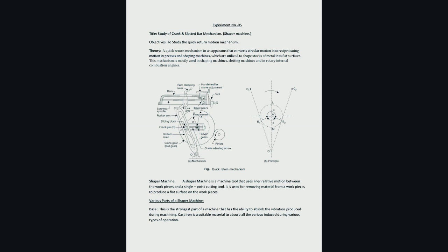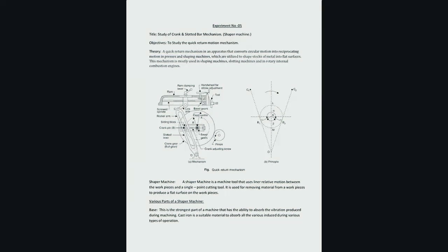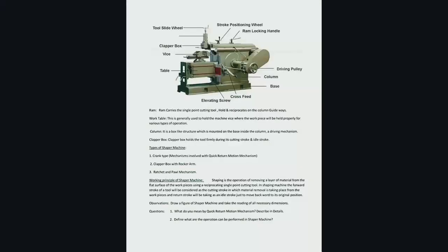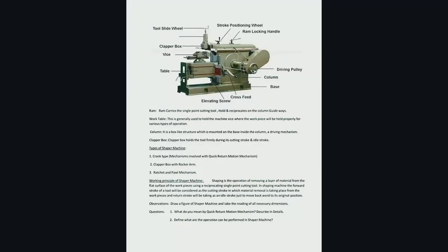Angle of ascent: the angle of rotation of the cam from the position when the follower begins to rise till it reaches its highest position is called angle of ascent. Angle of dwell: it is the angle through which the cam turns while the follower remains stationary at the highest or lowest point. Angle of descent: it is the angle through which the cam turns during the time the follower returns to its initial position.